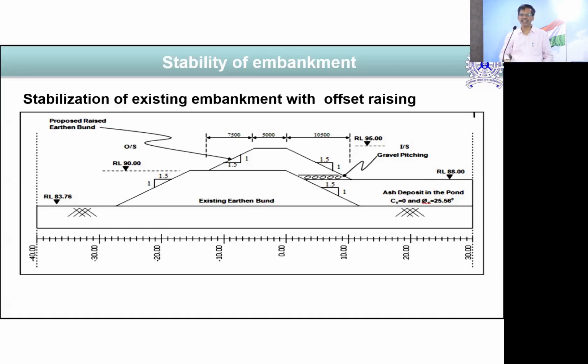But what about the bearing? If the bearing capacity is not sufficient, whatever the measure, make it 1:3 or 1:3.5, the overburden itself will not allow it to stand. Then there will be a vertical crack. That means it will settle down and the crack will be there like this. So it is not like a slope failure, rather it will be a foundation failure. That was the point when we were talking about clay soil.